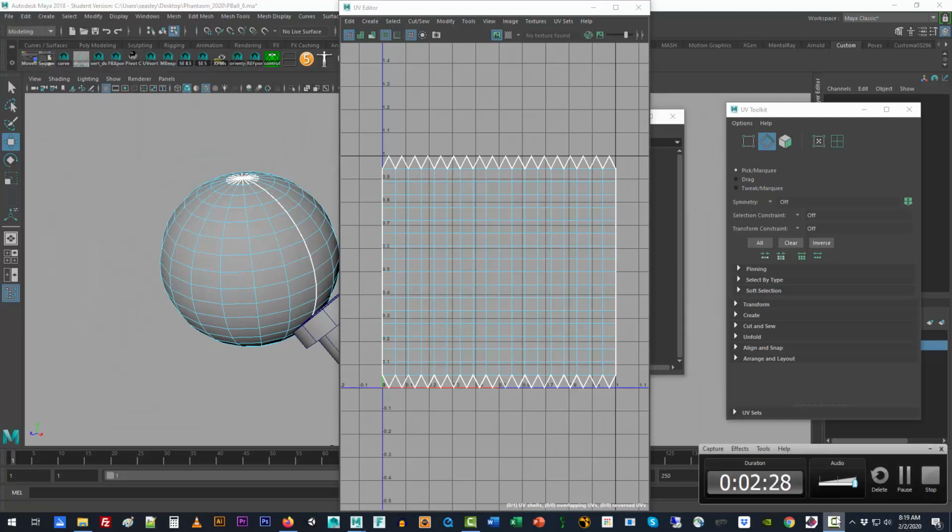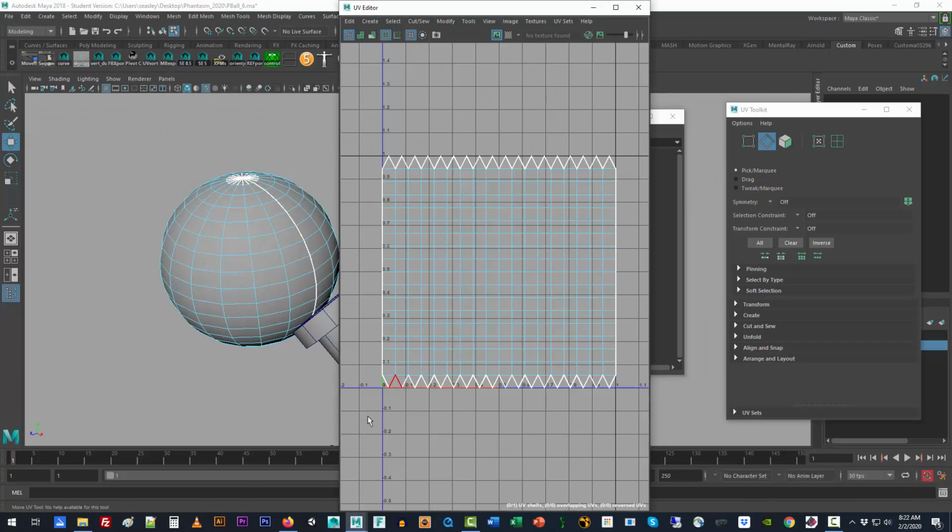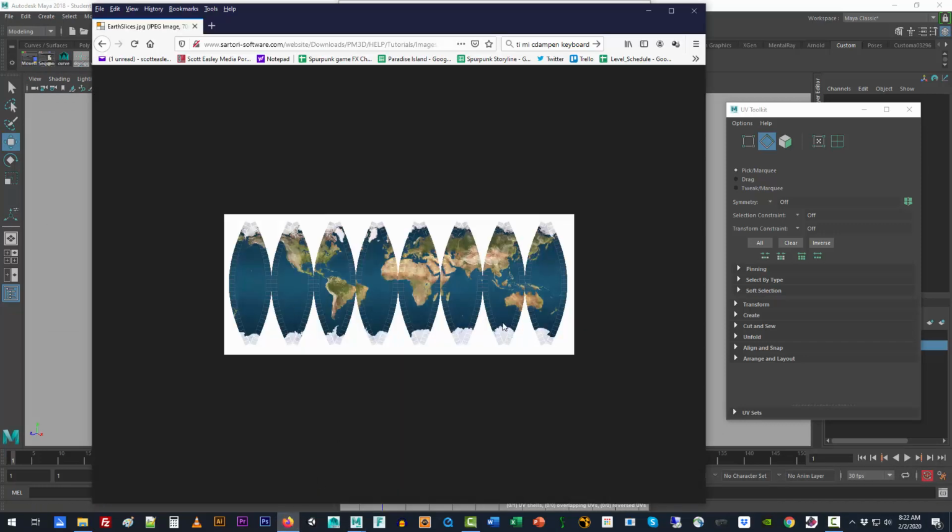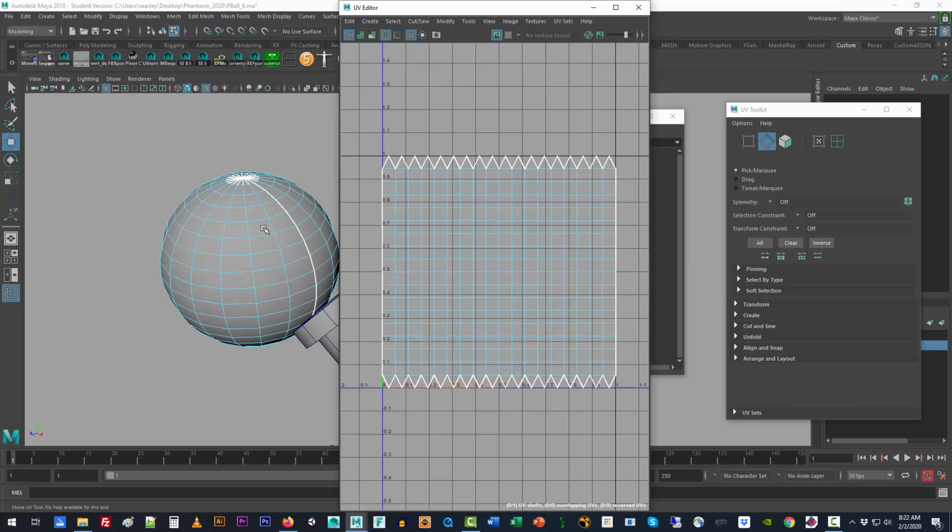One of the ways you can kind of see this best is these layout of the world. We need to know exactly where to cut along the UVs. And remember, we're not actually modifying the model, we're just modifying the way Maya thinks about laying it out. So effectively, as a foreman, you have told Maya, this is the way I want you to wallpaper this object here. And if you give Maya different directions on how to wallpaper it, the object stays the same, but your directions change.